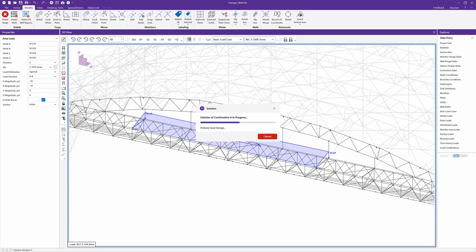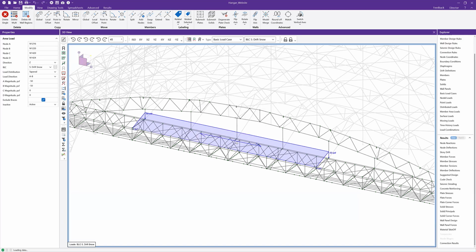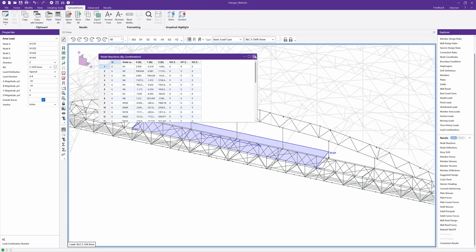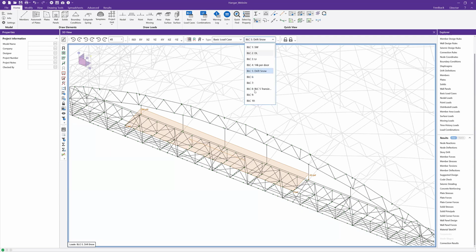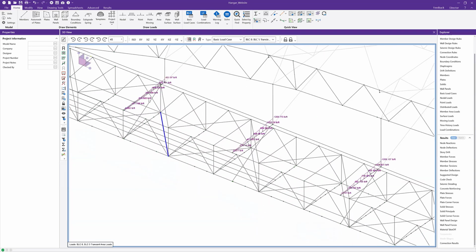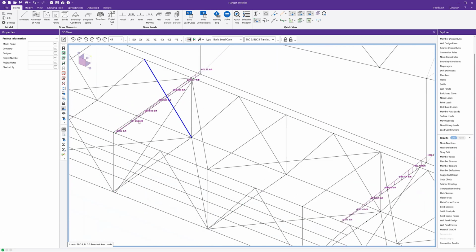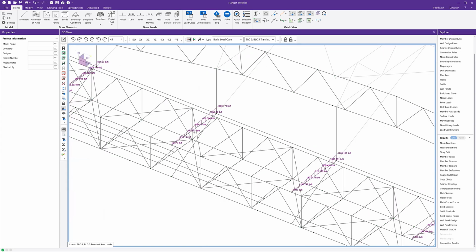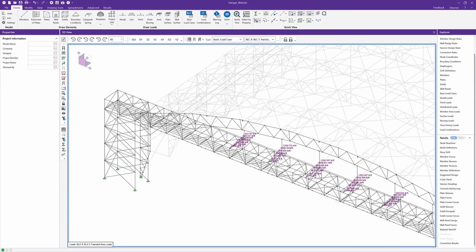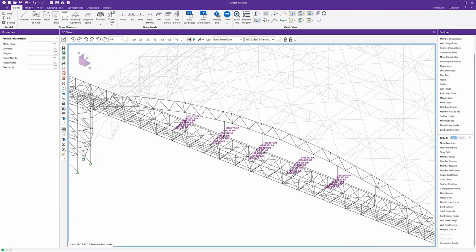What I want to show is the breakdown of the transient loads that are created based on the input I just created here. So that's our load distribution. Now I should have transient loads, and I do. And this is very clear now. This is what we expect to see, a linearly decreasing distribution of line load on those members. I excluded the braces, so it's not going to these braces that are in the same plane, but I have them directly to those elements. So exactly what I wanted, exactly what I would expect with that particular tapered member area load.